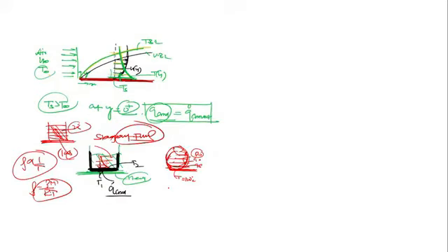Clear? Is this clear, Deepika? There is a current, because obviously if I'm talking about the different layers of the fluid, this layer is at 100 degrees Celsius, this layer is at 90, this is at 80, this is at 70, this is 60. The more the temperature, the lower the density. The density of the fluid on the bottom surface will be lowest. That will go up, it becomes lighter, and the vacant space is going to be filled by the high density fluid. This causes a current in the fluid, and that current is induced in the fluid because of difference in density caused by difference in temperature, and that is called natural convection.